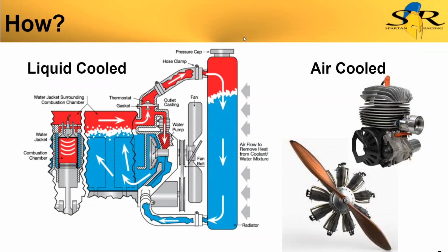So cooling internal combustion engines, there's kind of two types. There's liquid cooled engines and air cooled engines. Liquid cooled engines circulate a fluid through the engine to cool it down, and air cooled engines have lots of fins and air passes over it. Air cooled engines anymore are kind of relegated to smaller engines, motorcycles, lawn equipment, and airplane engines. The main reason for that is with higher performance engines, packing more cylinders closer together, it's hard to get enough cooling fins in there.